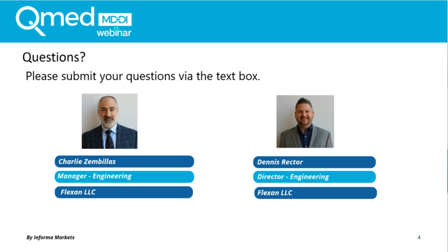And in addition to what Charlie said, generally silicone extrusion likes symmetry. So if you're trying to do a thick wall on one side and a thin wall on the other side of the extrusion, your extrusion will tend to want to distort or deform. It likes to be symmetric as far as the profile. But there are some exceptions to the rule, depending on the applications.